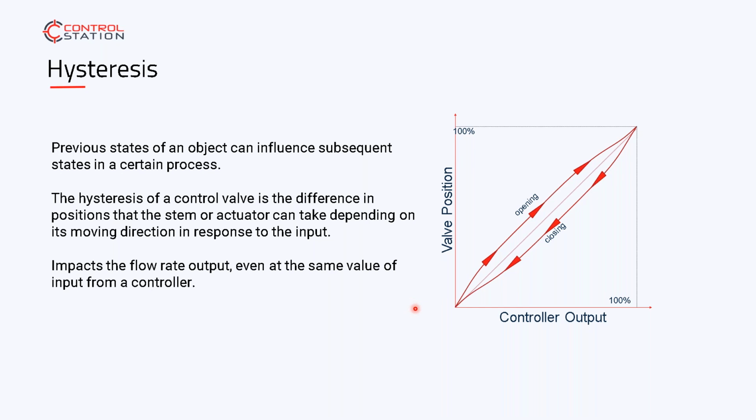Stand beside the valve with a finger on the stem of the valve and ask for a 1% change. Does the stem actually change? Does the flow rate actually change? So that you're making those connections between the virtual control system request and the physical control valve response.